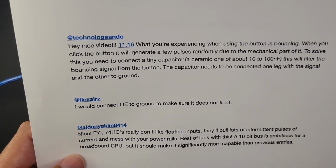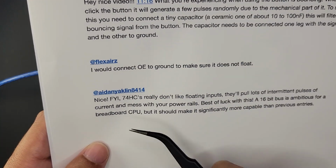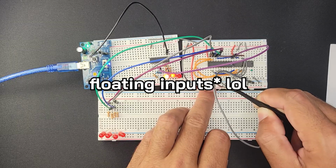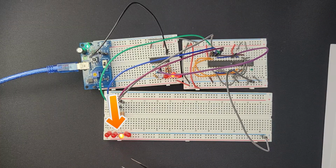But I got some really helpful comments that solve this issue. Flexair said I would connect OE, the output enable, to ground to make sure it doesn't float, and Aiden said the 74HCs in general just don't like floating pins. So when I do put this to ground, then we can suddenly see the counter start going upwards all the way. So really helpful comment. Thanks very much, Flex and Aiden.